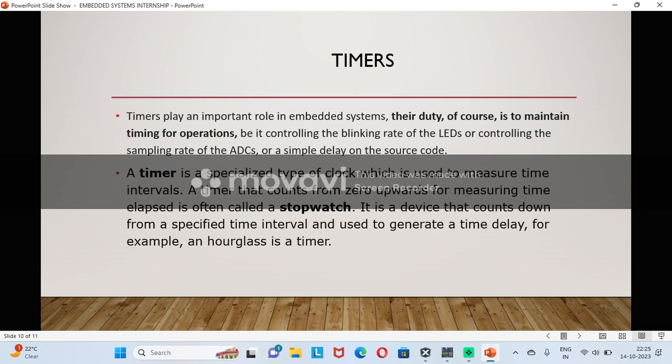But this register has a magical property. Its value increases or decreases automatically at a predefined rate. This predefined rate can be supplied by the user, or if not, it is selected by default by whatever application you're using. This timer clock's operation does not need any intervention of the CPU. They are very useful as they run asynchronously to the main core. This is a fancy way of saying that timers are separate circuits on the chip which can run independent of the main program, interacting via the control and count registers and something called timer interrupts.